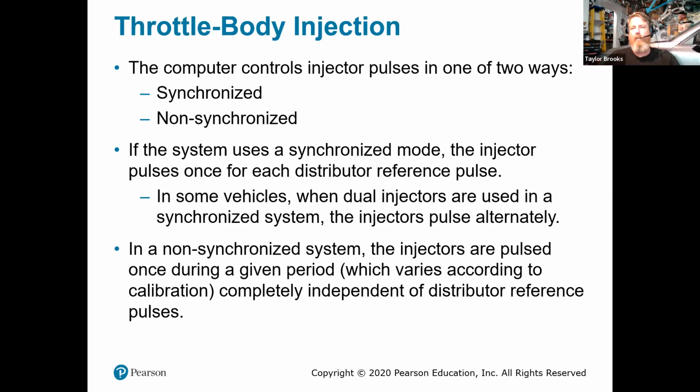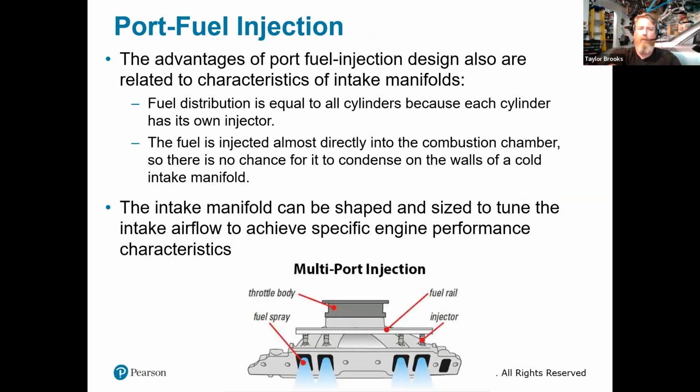However, as we found that there's better power output and better torque output with an open plane or single plane intake manifold, we went to non-synchronized, where it basically pulses all the injectors at a given time, to allow for the maximum amount of fuel to go in. Now, the disadvantage to that is we're very inefficient on fuel, because we are basically dumping in as much as we possibly can for the throttle load, obviously.